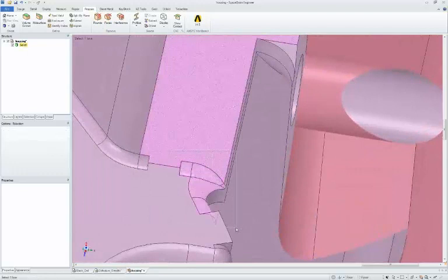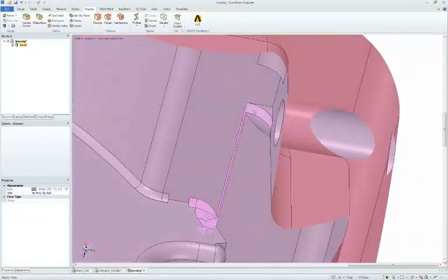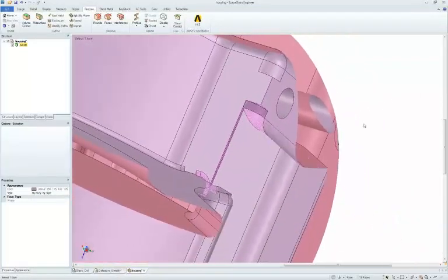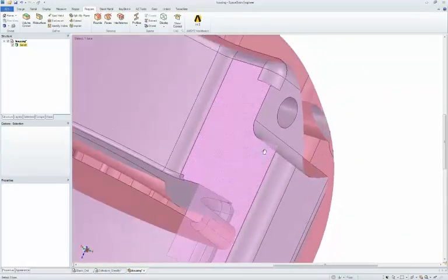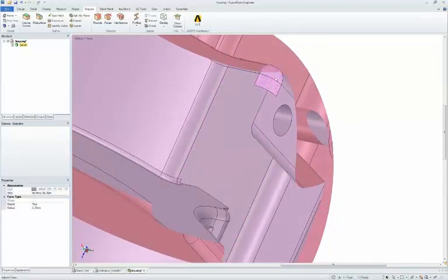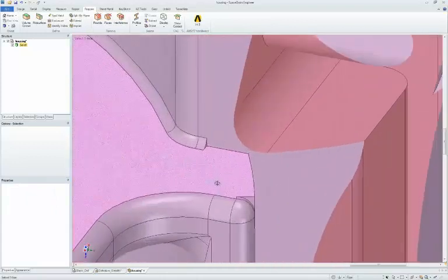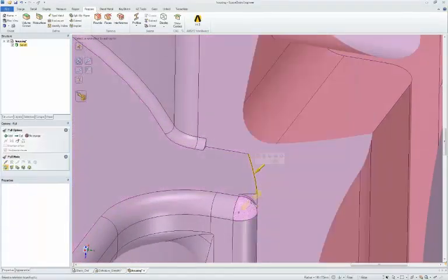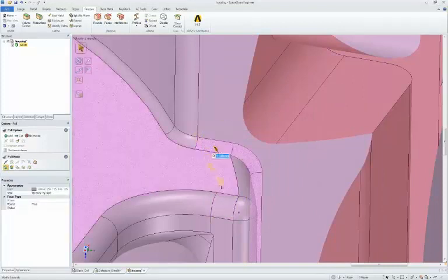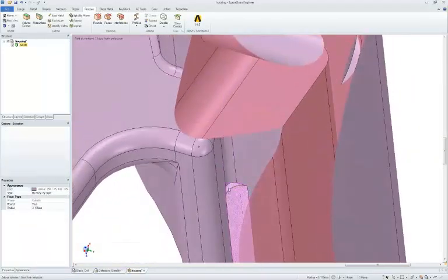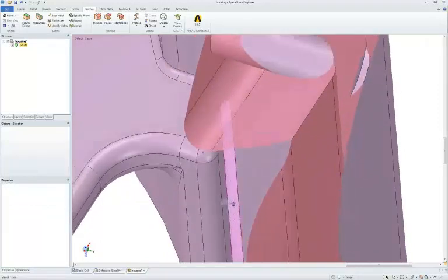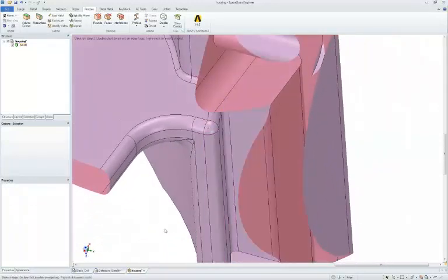A big box select will grab me all those faces, grab me those two thin sliver faces that are there, and with one fill, F, get rid of them. And now I can decide how this should look. Do I want this round back? Do I want to fill that in? Do I want to just pull this edge up to here? Or maybe I put a round back on around this edge, pull it up to here. Again, letting me put back, actually, maybe it's because of this, we had a bigger round here on the side. It's up to me. I can have it vary, I can fill in the bottom half that's there. What it does is it lets you have a lot of control over how you're simplifying and how you're getting geometry ready.